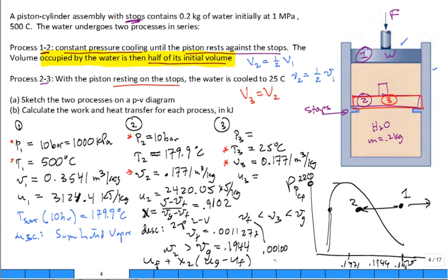How many zeros are there? And then a 29. And V sub G is 40.36. All right? So I see V3 is between V sub F and V sub G at that lower temperature of 25 degrees C. Hence, I get the quality at 3.